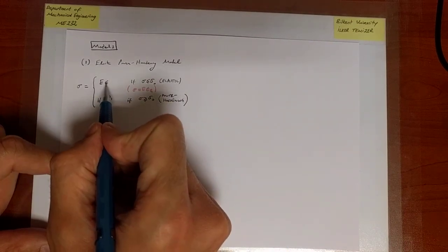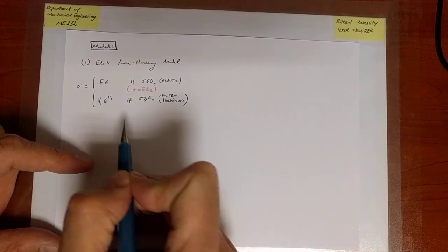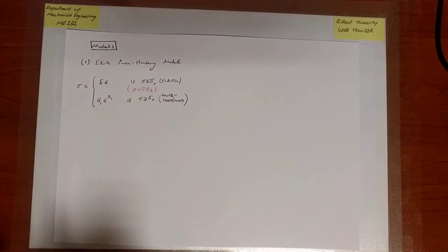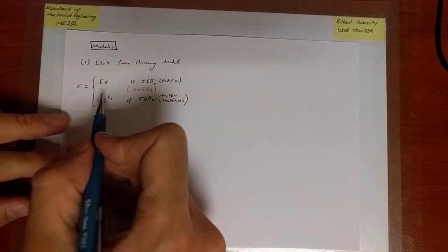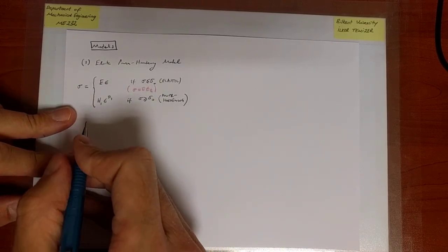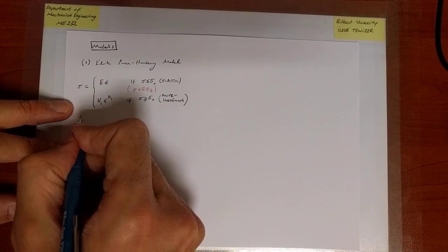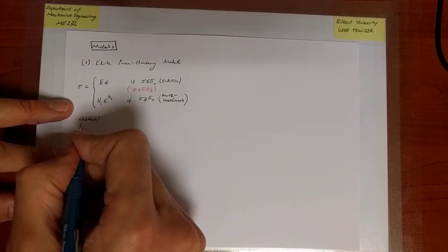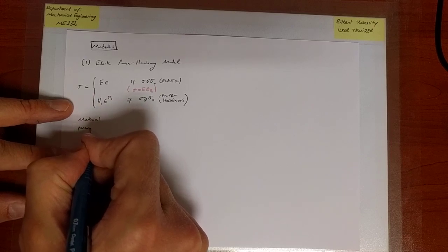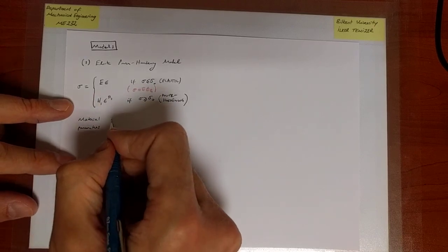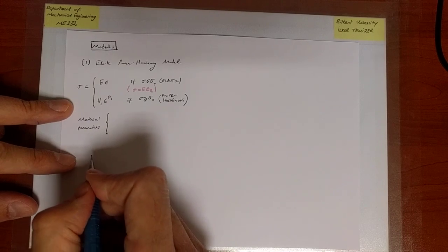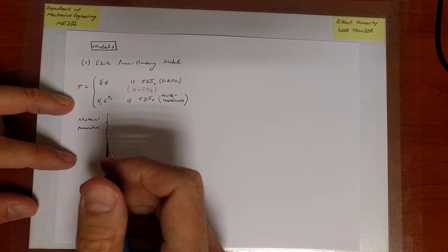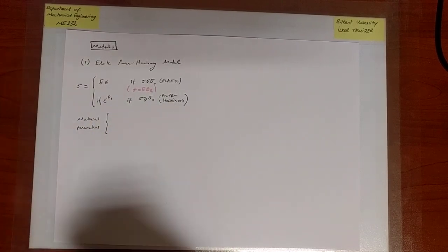In the elastic region, epsilon is of course equal to epsilon E. There is no difference, but that's not the case in the power hardening region. Okay, so here E is the Young's modulus, that's clear, but we have now two new material parameters. These material parameters are modeling parameters, and we have just two parameters, H1 and N1, so we have only a limited minimal set of parameters that captures the essentials.